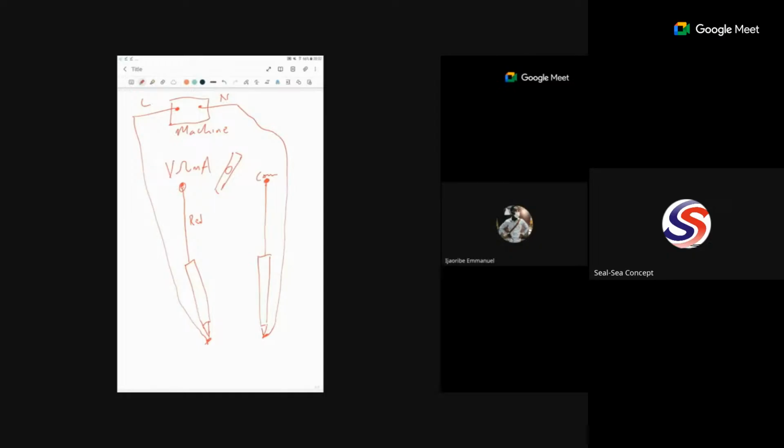So that if you want to test for, let's say, something that is more than 200 volts, and you are now setting your probe to where they wrote the maximum of what? Maybe 150 volts. So you can see that you will damage that multimeter, because the amount of voltage that you have set to is lower than the voltage that will flow through it. So you must set it to what? A correct voltage for that particular measurement.